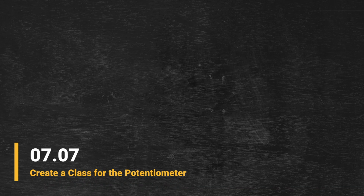In this lecture, we will wrap up our hardware components by creating a dedicated class for the potentiometer. Instead of calling analogRead directly in our main code, we will encapsulate that logic into an object that can provide us with refined data, such as a mapped brightness value ready for our LEDs.